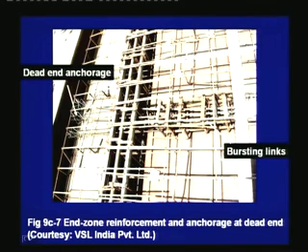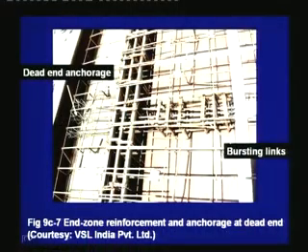This is the detailing of the other end, which is the dead end, and see how the tendons have been enlarged to create the anchorage at the dead end. And here also you can notice the spandrel beam with closed stirrups, and also you can notice the end zone reinforcement to check the bursting due to the concentration of stresses.